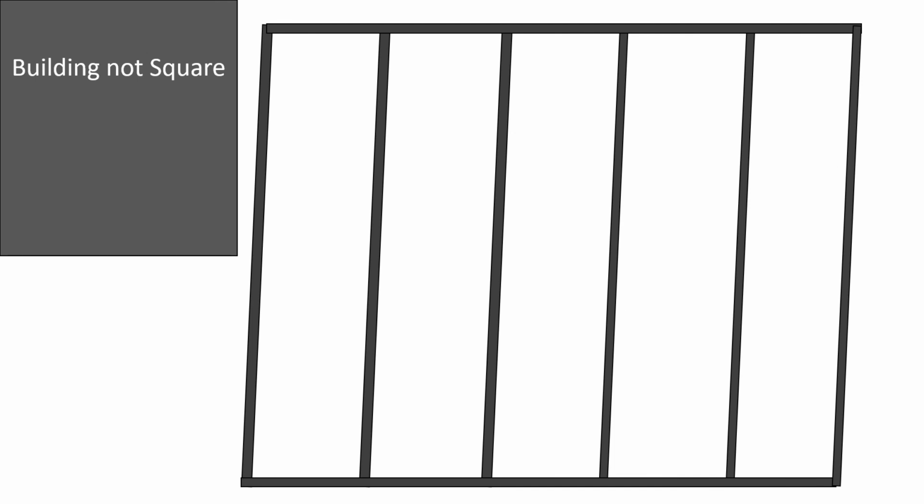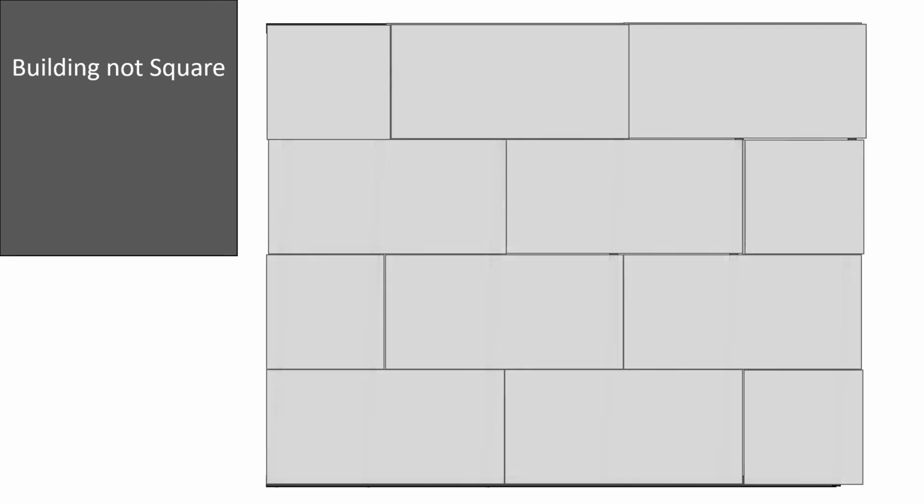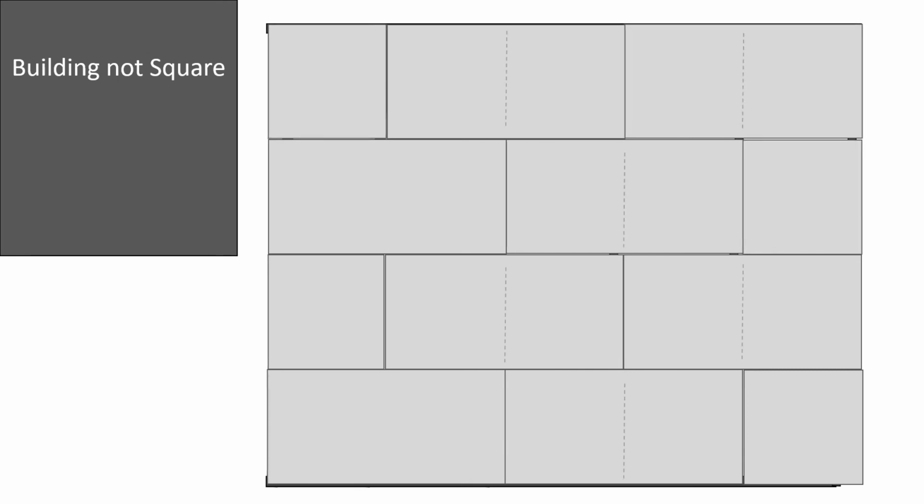And for the last example here, you have a floor system that's not square. And while laying the plywood for the subflooring, you'll experience some pretty bad problems. So you get the first line of decking installed. All right, here, all the subfloors are in place. And when the decking is laid, the joists are covered so you can't see them. But each sheet will be nailed at the ends here. Like this is a sheet of plywood. It'll be nailed at the ends.